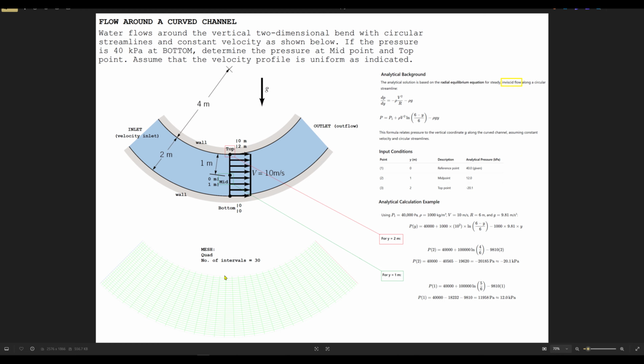For creating and generating the mesh, we will use a quad mesh, and for all of these edges, we will use 13 as the number of intervals, as you can see here. All right, that's the setup for our problem. In the next step, like in the previous sessions, we will start with Ansys Workbench, build the geometry, and prepare the case for simulation in Fluent.